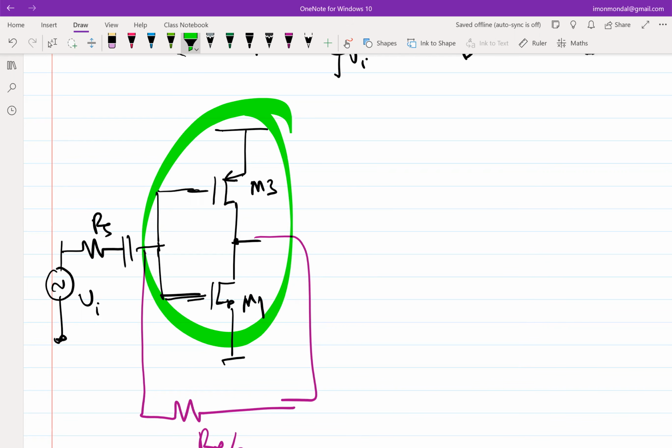Do we use that amplifier in any practical application? Yeah, nowadays it's very commonplace simply because VDD is very low in today's technology, right? 1 volt, 1.1 volt, sub 1 volt. Which means that using resistors is out of the question, which means you have to use a current source, which means you anyway need to put a PMOS on top.